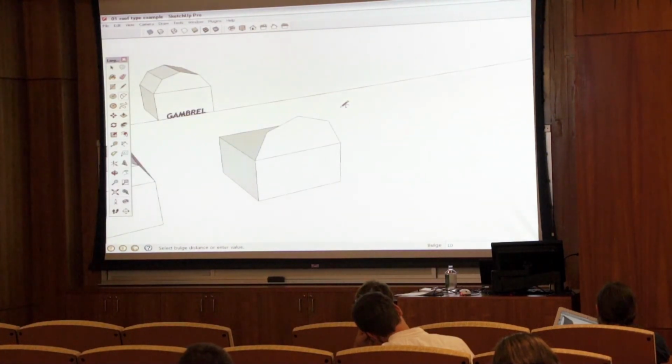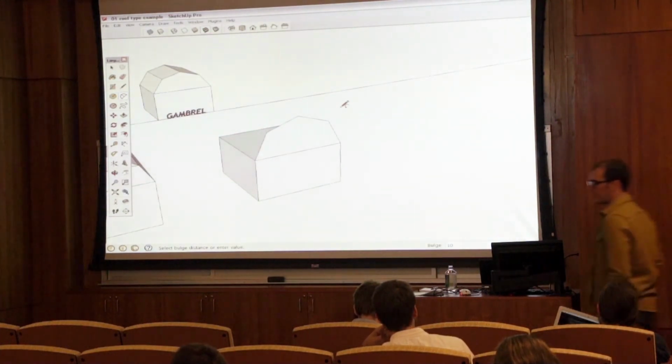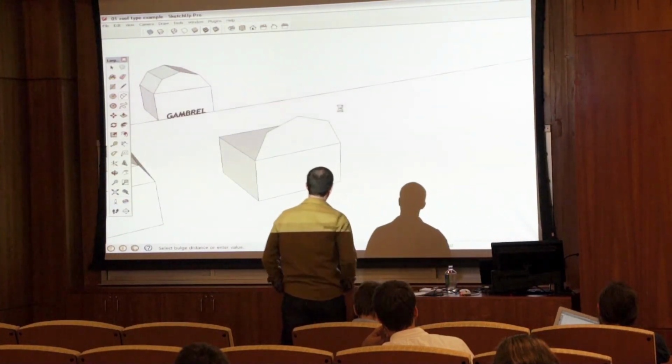See how some of you still have it as 12 sides. You can take the select tool and select the edge and go to Entity Info and then adjust the number of sides to 4. If it's not working, then just undo and click on the arc tool again, and before you begin drawing it, set the number of sides to 4.